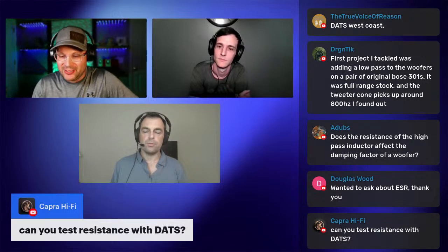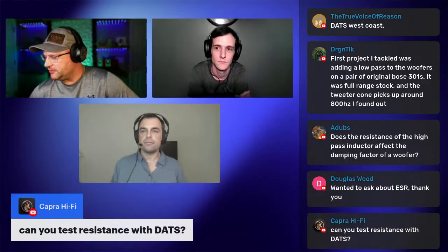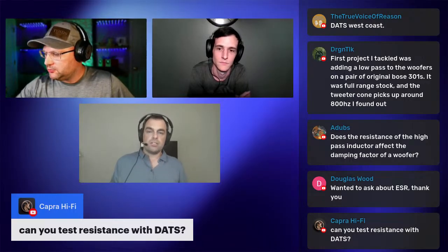Sure enough, completely shorted out, dead on arrival. It happens. That saved me a whole lot of time because otherwise I'm taking the other crossover out of the other speaker. Was it an inductor that was short? No, it was a capacitor. Oh, really? The first capacitor, yeah. I know it seems odd that a capacitor would be that way. Yeah, you've got to be careful with inductors, just so people are aware.